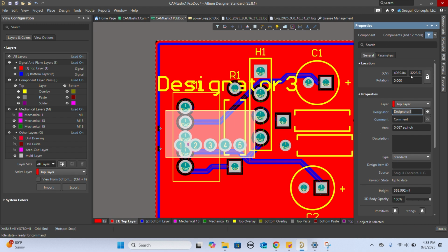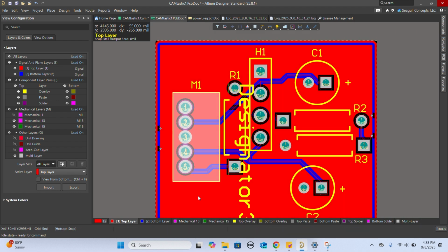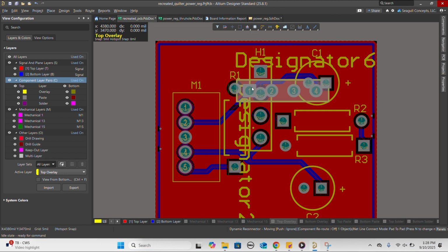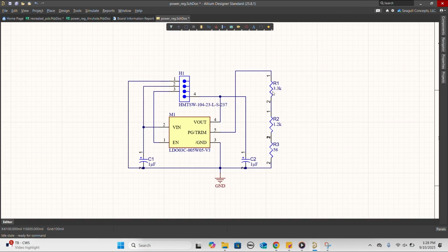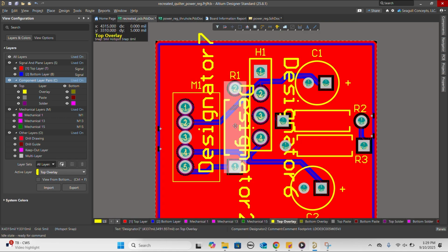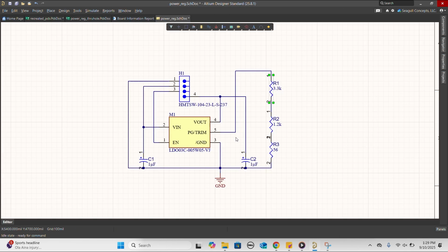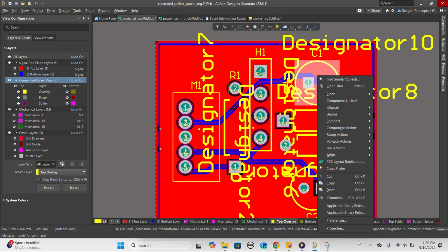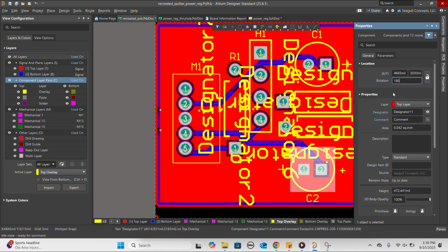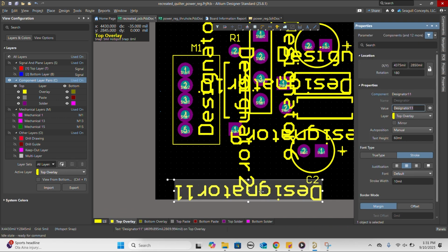I'm just going to rotate them, and now you're going to see a time lapse of manually rotating and adding all the rest of the components. As you can see, we have the footprint, and we're adding those according to the outline. You must have the components and associated footprints saved to the component library for this to work. With all the parts available, you right click on the board, place component, search for the part, and then drag and drop, and repeat the process for the remaining components. So for the capacitors, for the header, and then for the chip, we're going to continue to do this.